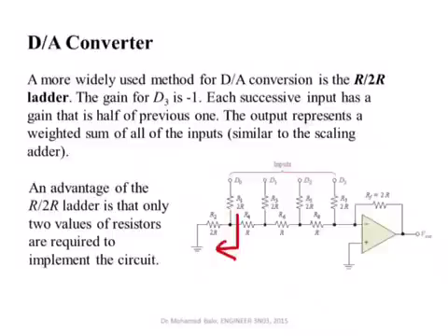I can replace this by a voltage source in series with a resistor, and this resistor becomes in series with R. Then I come again at the next point and do a second Thevenin equivalent, so all this circuit to the left of this plane is replaced by a Thevenin voltage source and a resistor, and I repeat the same here and here. At the end you will see that the resistance seen at this point is simply equal to 2R, so it's equal to this one.